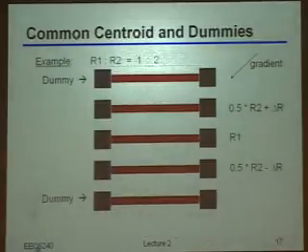That's actually shown in this picture here as well, where I'm going back to the simpler unit element with everything in just one direction, but pretend I could expand it to do a better job with that. You'll notice that I added these so-called dummies that aren't really doing anything, except to make sure that the local environment around each individual unit element really is exactly the same. Okay? Does this make sense to everybody?